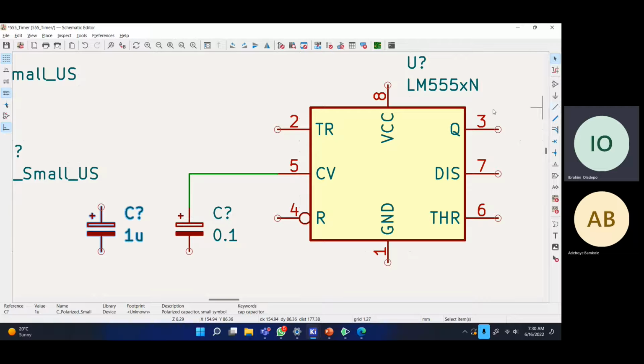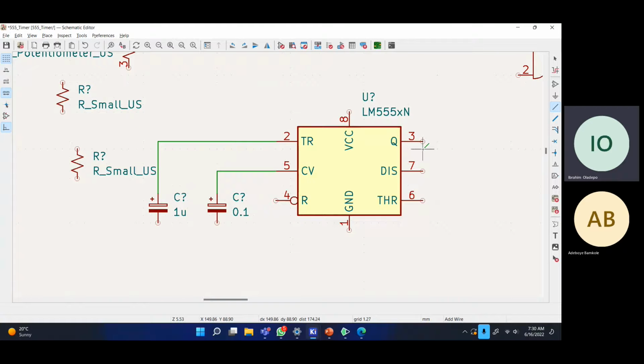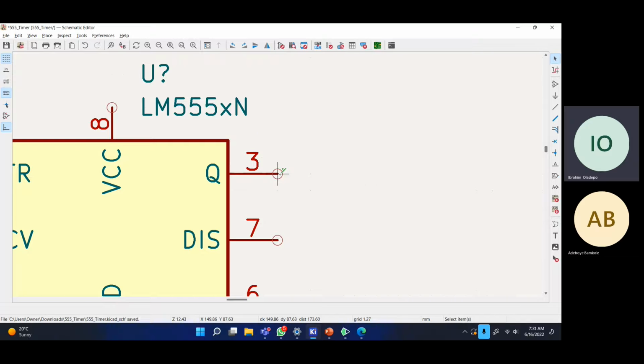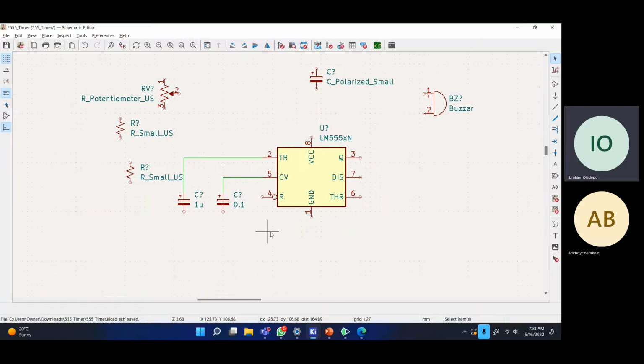Another shortcut for that is you can press W. When you press W, it just starts wiring. So you can come to this point and then press W, and then you can wire that. But I think a new feature is that even when you're in the select option, once you place the cursor on top of this circle, then you can wire directly without any extra commands.